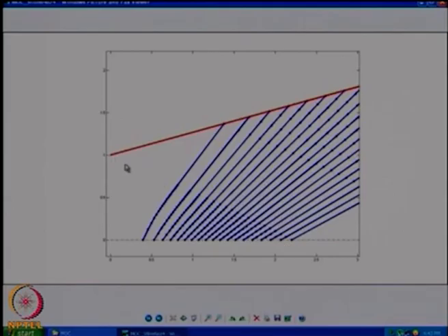After that whole thing, you will find that I have started with 20 points, so from here you will have 20 points along this overall. Now the next thing I need to do: this point is now useless, its job is already done. The next point here, I can send to the wall. I do a wall point calculation here. From there, that point and this point together, I do an interior point, and I get this point. With the next characteristic line point, I get an interior point like this, and I just keep on going along this line. That is this picture. Now I also want you to look at one more detail. The very first characteristic was vertical, and the second characteristic was here.